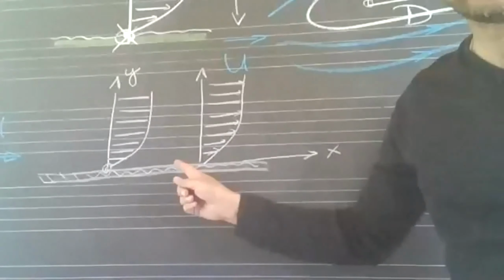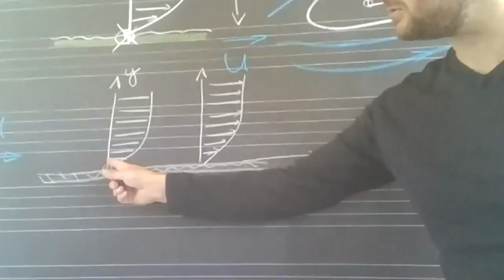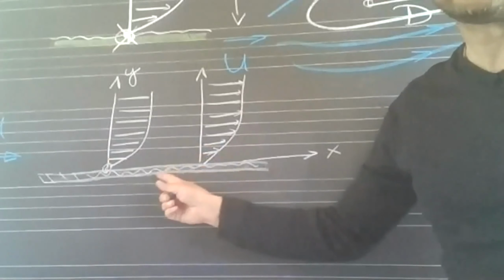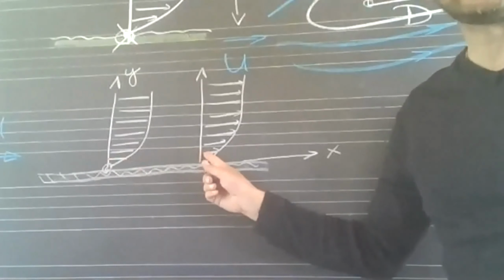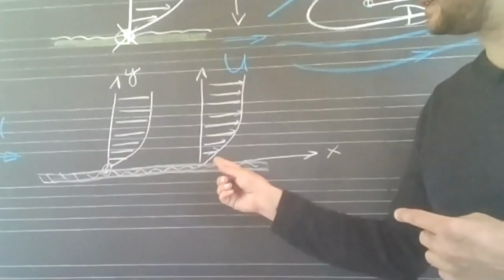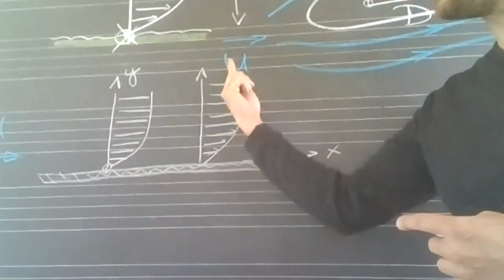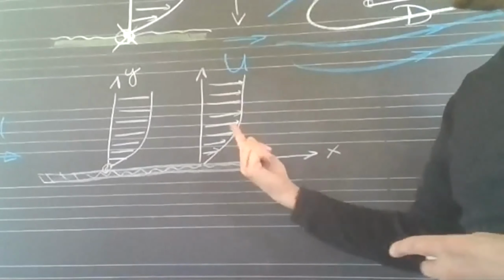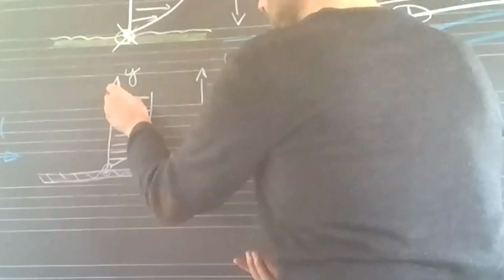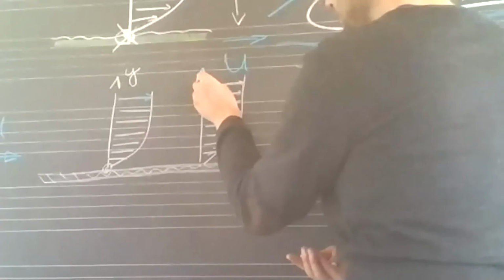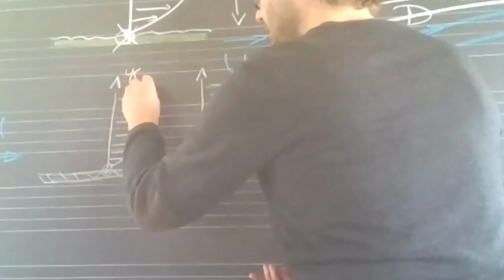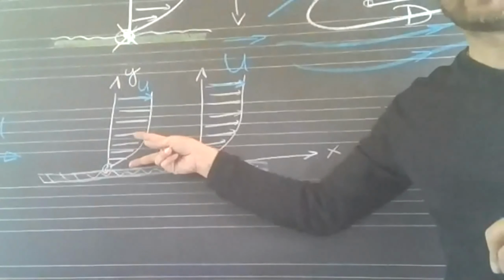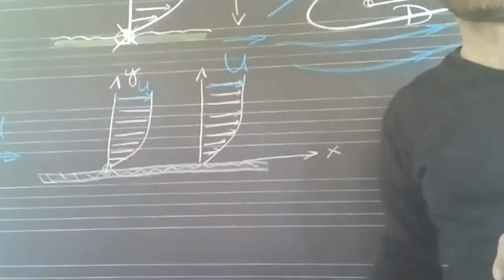There is some change, and we'll see this in a minute, but the change was very, very slow. So he says the second derivative in x direction is small, and he neglects it, but the change in y direction is quite rapid. It goes from 0 to a high velocity, out here, far away from the wall. You must have capital U. That is quite rapid, especially if the boundary layer is thin.